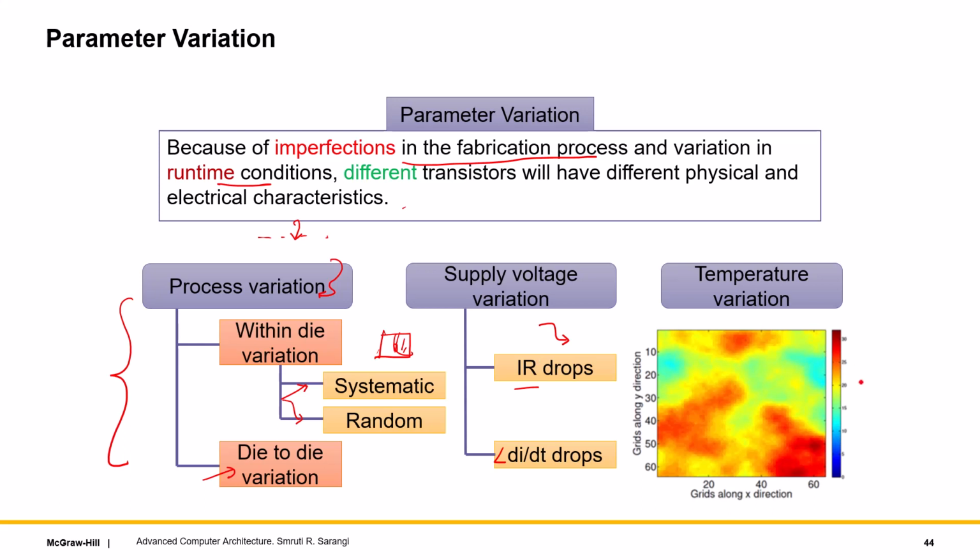And then of course temperature. So go back to chapter 12, you will have high temperature regions, low temperature regions, and then different temperature values lead to different transistor speeds, which lead to different values of the leakage. So the leakage feedback loop also comes into play, but fundamentally, by and large, the temperature variation across a chip will impact the performance, right?